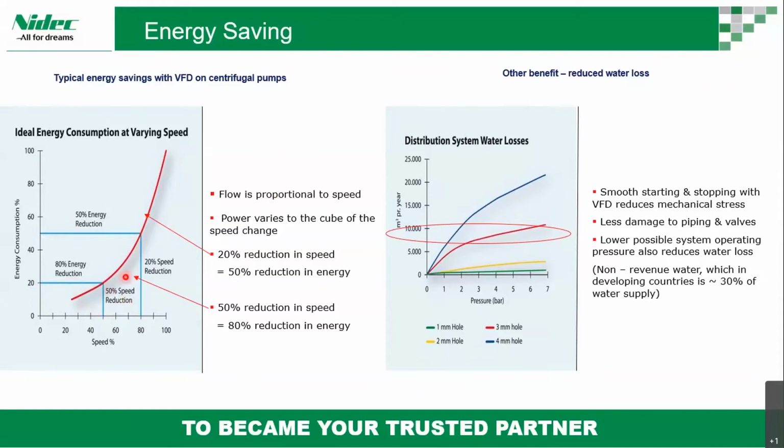Water flow always varies, so we can save energy by putting in a VSD. And second, every piece of equipment gets designed a little oversized to take care of critical situations. That itself saves nearly 20 to 30% of the energy.